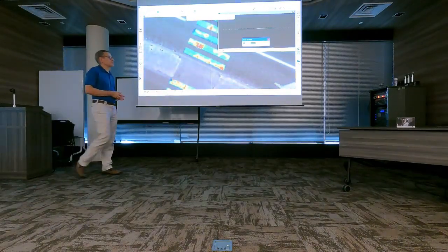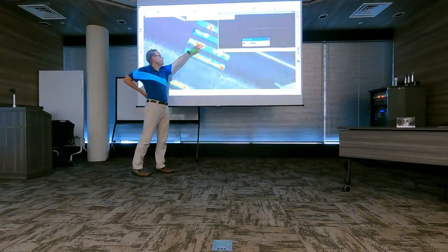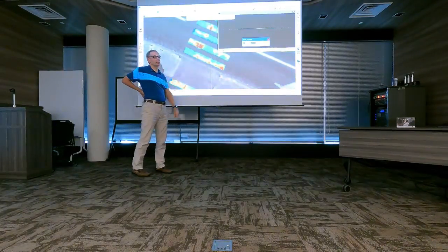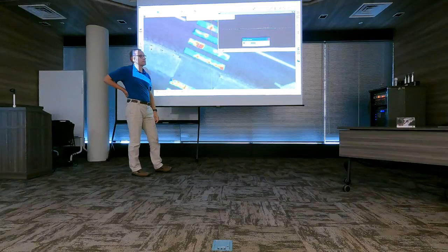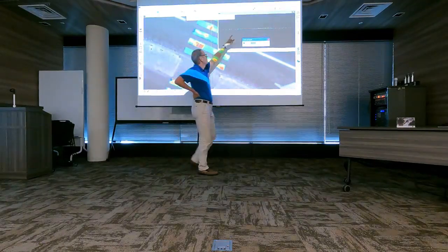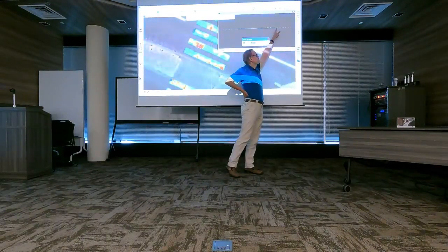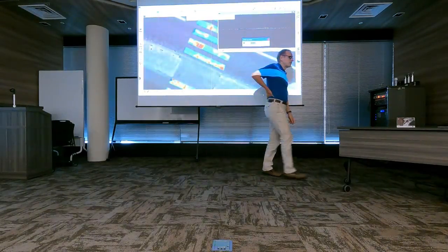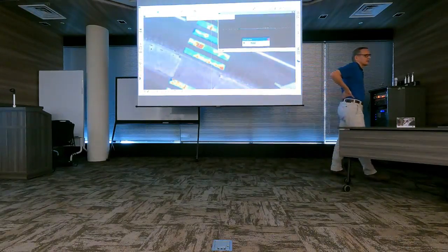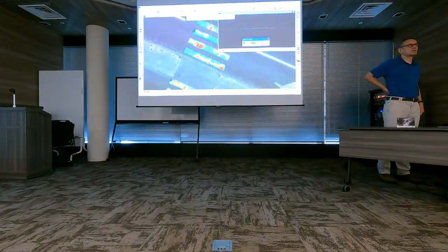But so the software decides on a radius for a circle, radius big enough so that we get some points from outside the paint polygon. And these points outside, so these points here and here, those are used to fit a plane equation. So we get a plane equation, which is our understanding of the underlying asphalt surface.